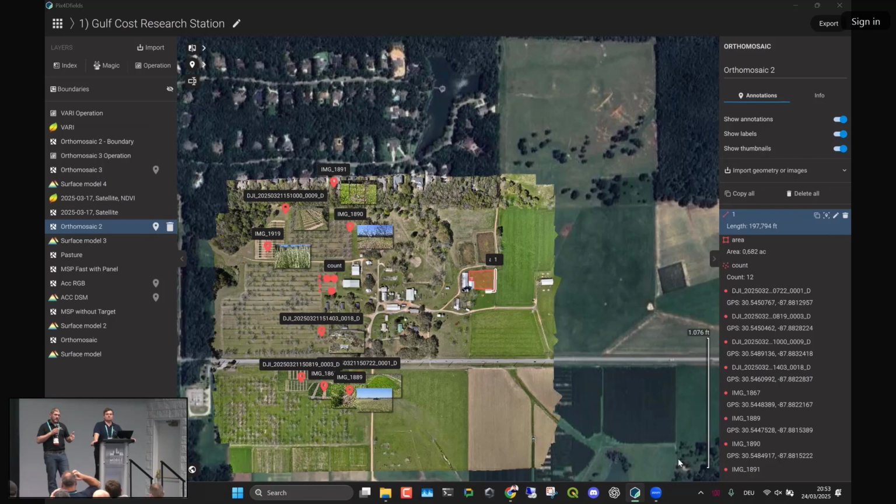It's a very powerful troubleshooting tool, because when you see it in the imagery and then line it up, that's why I record every pass with my equipment anymore, because you're not really sure. I don't remember what I tilled at. And you see some of those machine patterns, because I use the measuring tool in here and I measure, and I'm like, that was exactly a 45-foot swath, and it's repeatable across the field, and I'm betting that was my field cultivator.